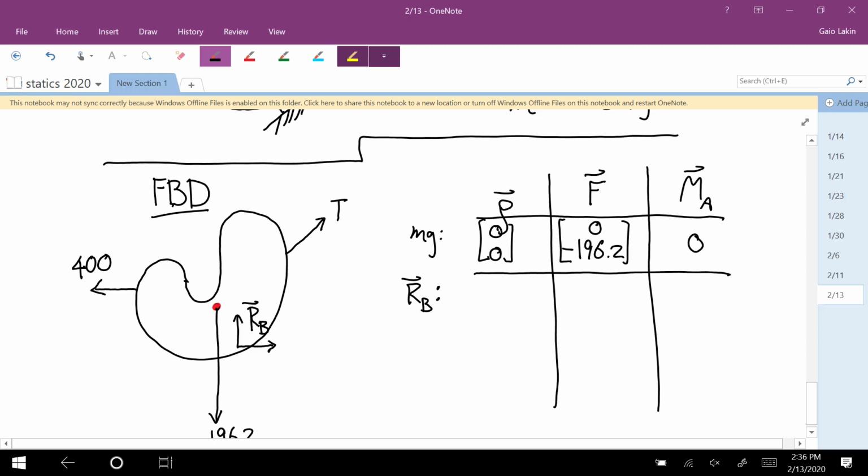The rho vector is the vector from the about point to where the force is applied. So if your about point is the origin, the coordinates are the rho vector. Does everyone see that? That's not always the easiest way to do it, but in a problem where you're given coordinates for everything, that often is the easiest way to go. You don't have to recalculate anything about those rho vectors.